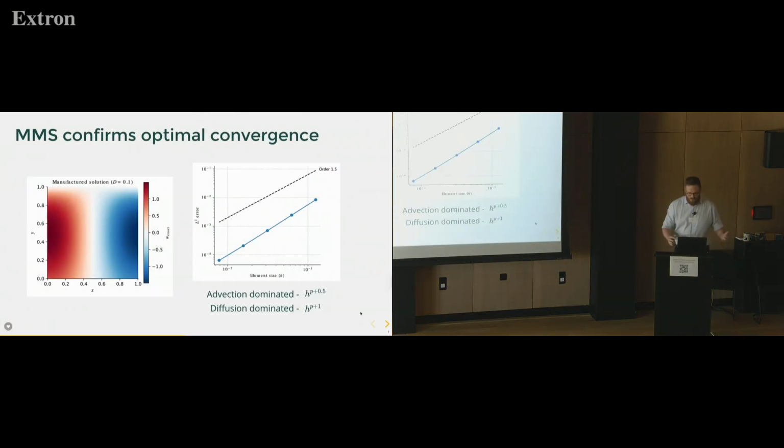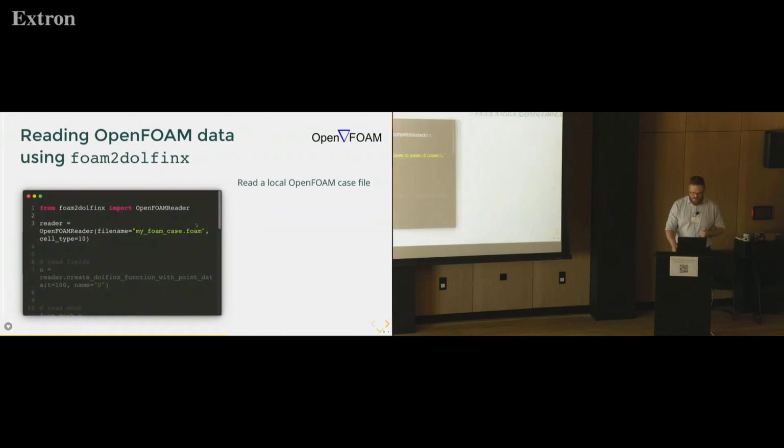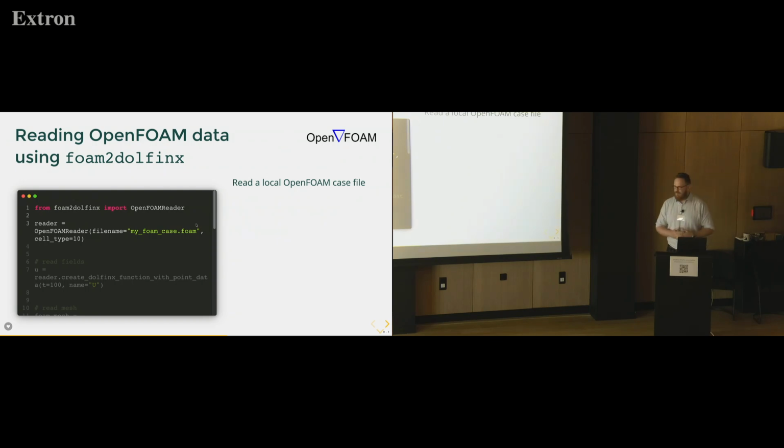All in all, we did some manufactured solutions just to ensure that our problem is scaling properly, showing that in advection-dominated scenarios we should be scaling with h^(p+0.5). And things seem to be working out all right for now. But as I mentioned before, you can verify everything works quite nicely when using analytical velocity fields, but when we're designing these engineering components, we need to use real velocity fields of real components, and so we're trying to use more widely used software like OpenFOAM.